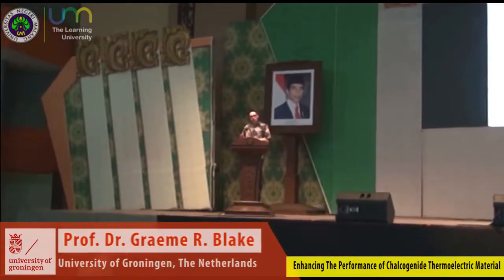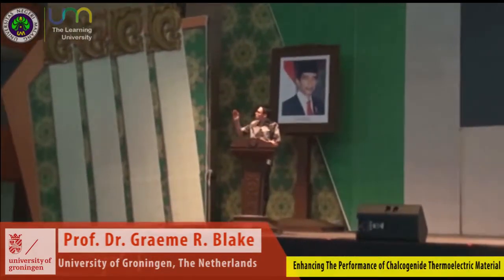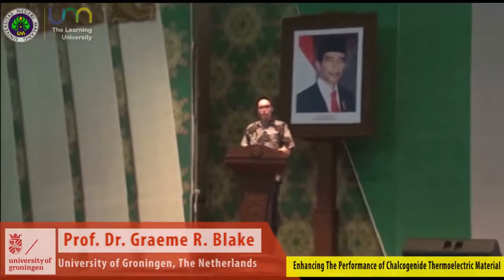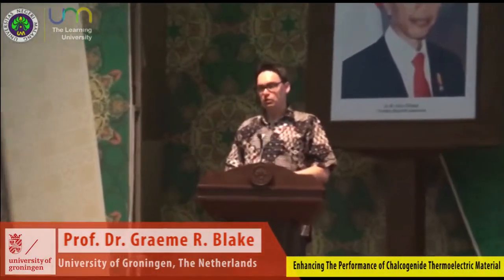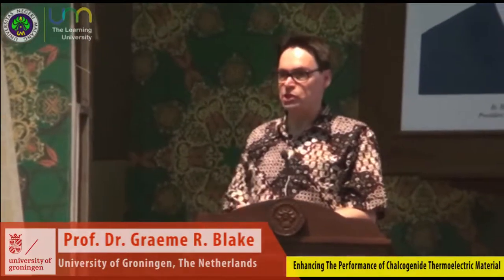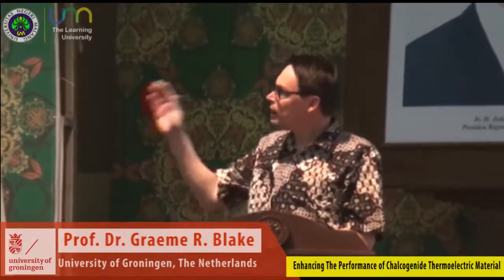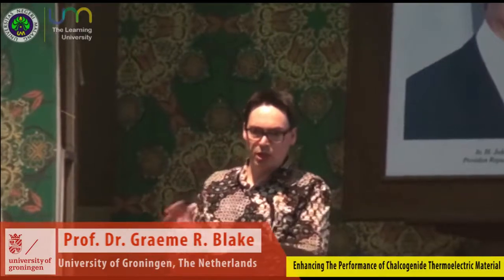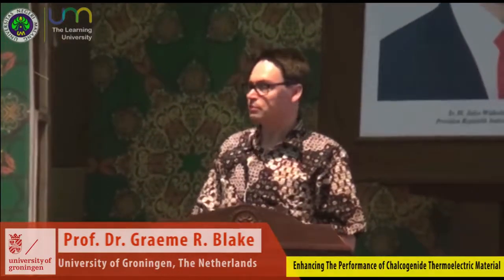So basically, what we're looking for is a so-called electron crystal phonon glass material. So it means a material which is highly ordered with respect to carrier transport. So it conducts electricity well, but is glassy with respect to phonon transport. So we want phonons, which carry the heat through the material, to be scattered easily and blocked from propagating long distances. Next, please.